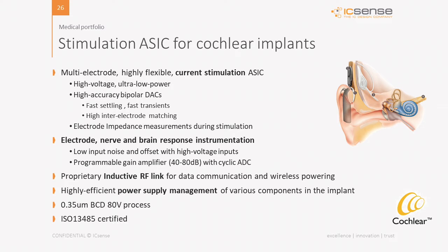On the other hand, there is also a lot of sensing, so we are able to measure the electrode, the nerve, and the brain response with a readout chain. The chip also includes a proprietary inductive RF link, which can be used for data communication and also wireless powering. And as such, the chip contains a very high efficient power supply management that can also be used to generate the power supply of various components within the implant.